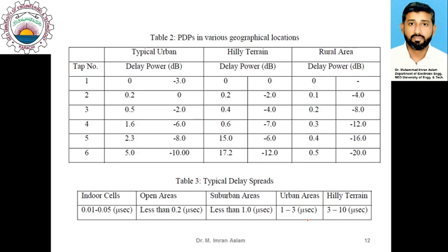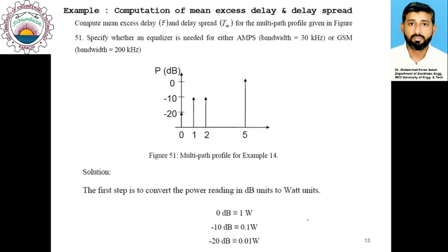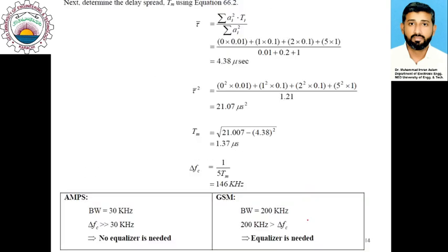The frequency domain version of this delay spread is the coherence frequency or coherence bandwidth. Coherence frequency determines how much frequency channel possesses, or in other words, this is the frequency where different phase amplitudes are correlated with each other, and beyond that the phase amplitudes are uncorrelated with each other. Okay, so this concludes our discussion on this topic.